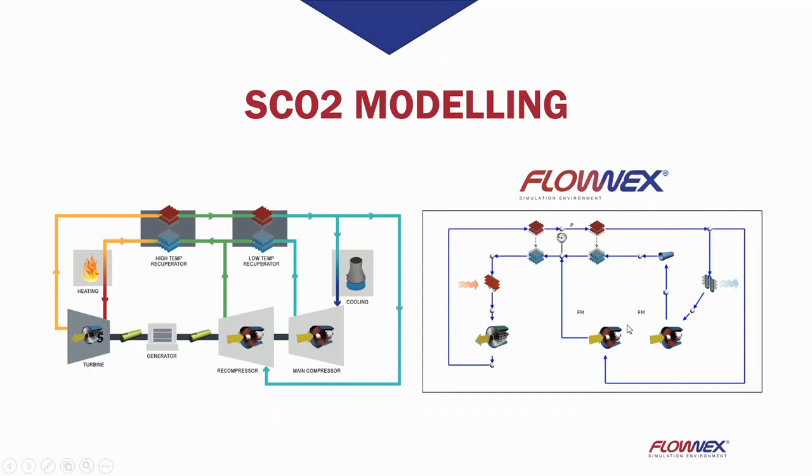The recuperator can be modeled by using a simple heat transfer or via a more complex heat transfer correlation such as the Dittus-Boelter or Gnielinski correlation for convective heat transfer. Ambient conditions can also be modeled for the pipe element to simulate the effects of having an insulated versus a non-insulated pipe. The heat source and cooling can be modeled by integrating other cycles into the network, but more on this at the end of the webinar.